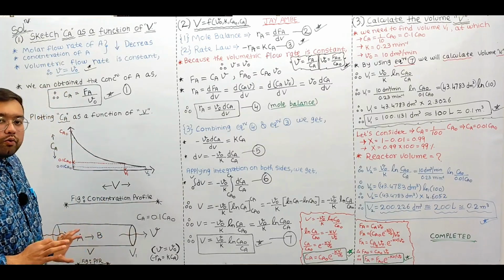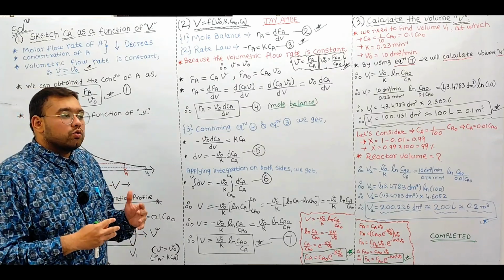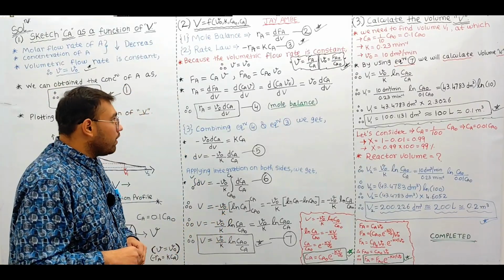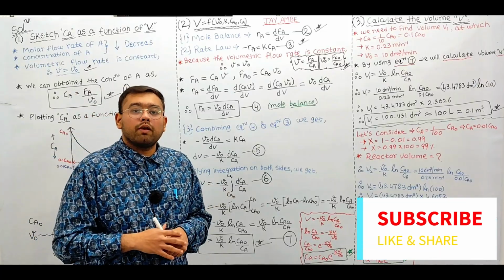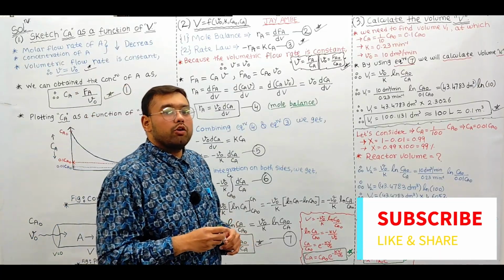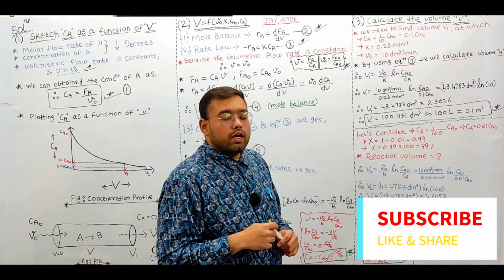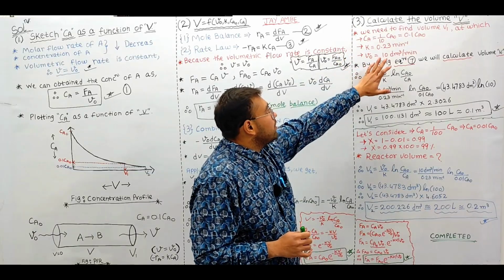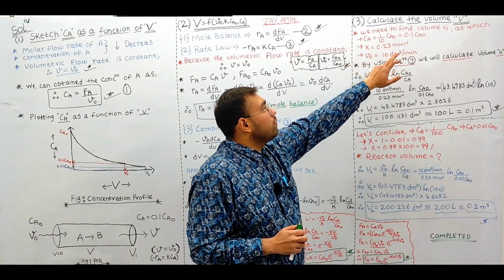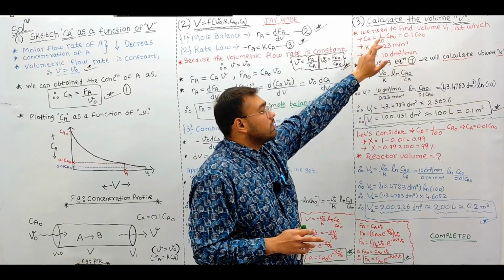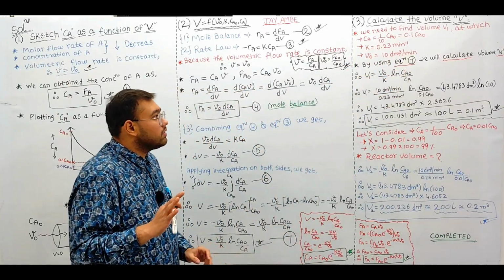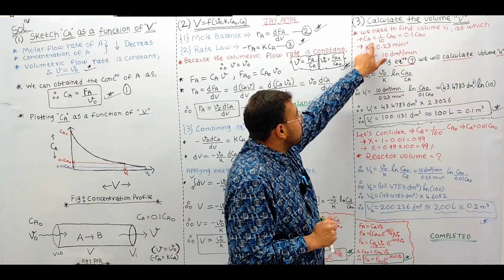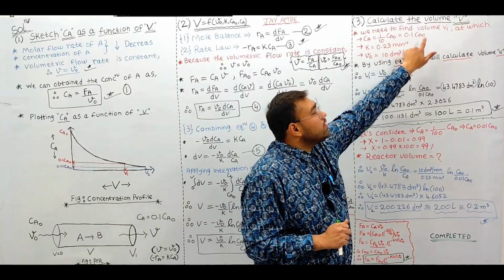So by using the plug flow reactor, we are aiming to achieve the desired conversion of 90%. How large a volume of plug flow reactor is required in order to achieve the desired conversion of 90%? So we are solving the third part. Let's say we need to find the volume V1 at which the exiting concentration is 10% of the initial concentration.